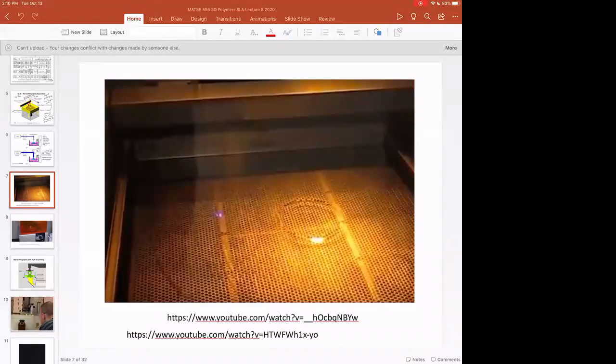Thermosets, even though they're called thermosets, maybe we can call these photosets because they're not thermally polymerized in general, they're photopolymerized, but thermosets and photosets are the same class of polymers. Thermosetting polymers can't easily be melted, they can't be reformed. Now they can be ground up, but they're not reactive once they're ground up, so they're basically just dead polymer powder that can be used as filler or something else. So there's different things going on with these thermosetting polymers versus the thermoplastic polymers that we've discussed before.